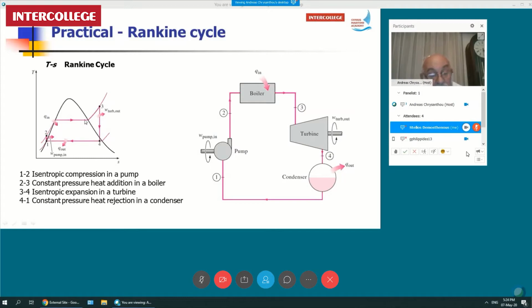And also we can see from here that we get much higher efficiency of the boiler, and we allow the boiler to produce more steam, or rather produce superheated steam, raising the temperature higher. So if we have a higher temperature and a greater temperature difference between the higher reservoir and the lower reservoir, we have a bigger work done. Is it clear now? Now, this cycle here is called the Rankine cycle.